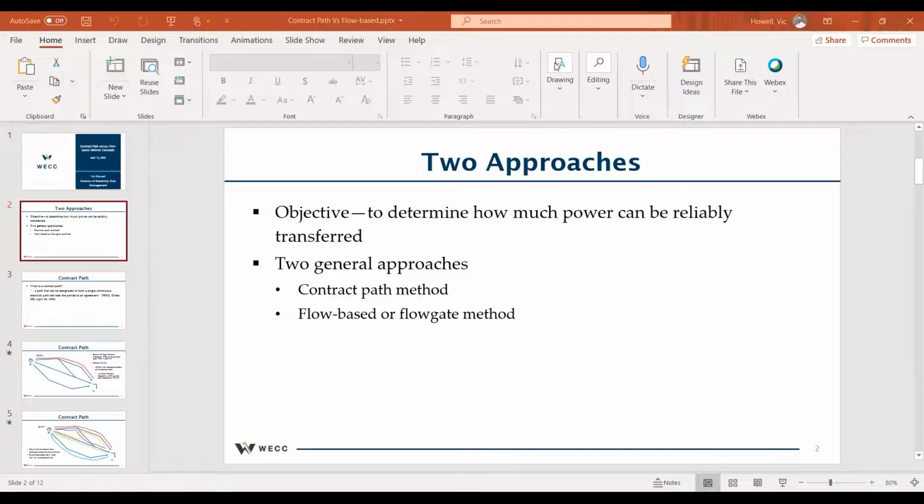So the way that it works currently in Washington, a developer would buy transmission for like 100 megawatts and would pay for it every hour of the year, even though it's only used 35% of the time, or whatever the capacity factor is. So a 100 megawatt flow gate could only ever support a 100 megawatt wind farm, even though that wind farm does not operate at max capacity.